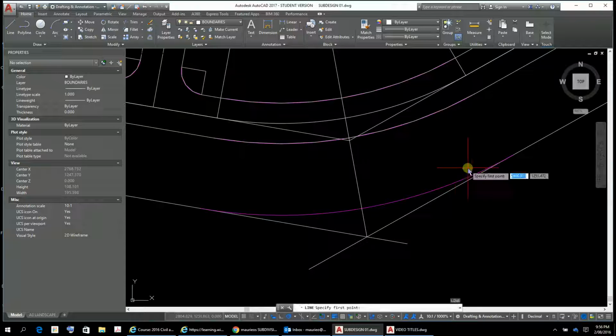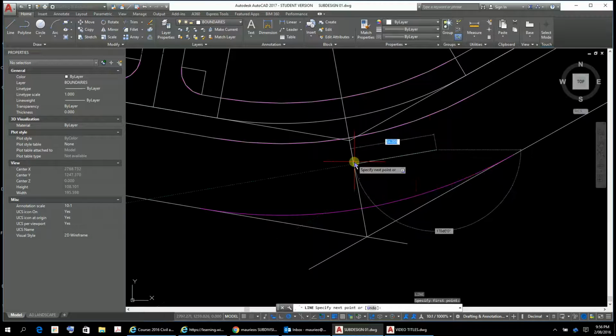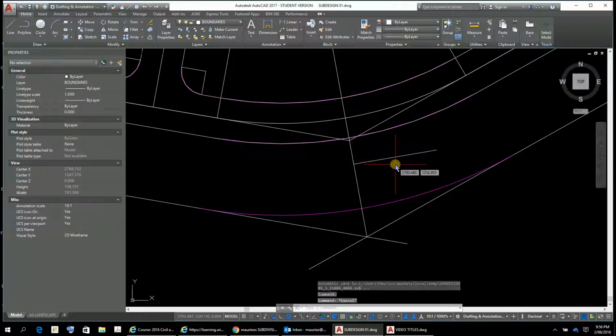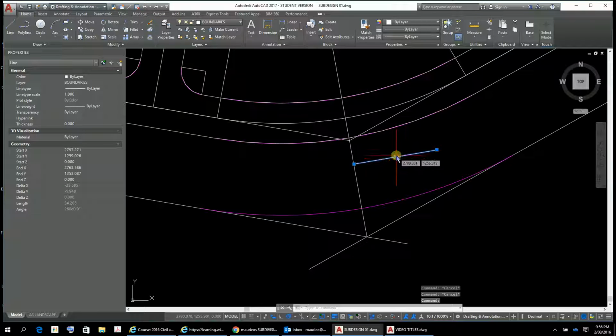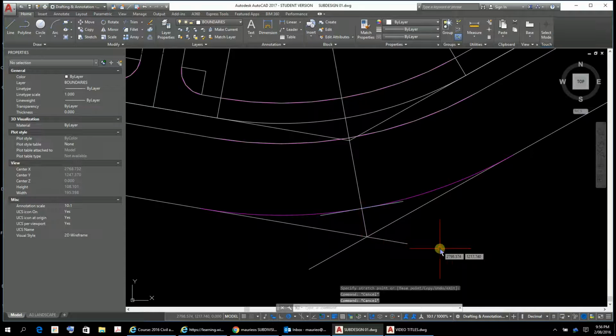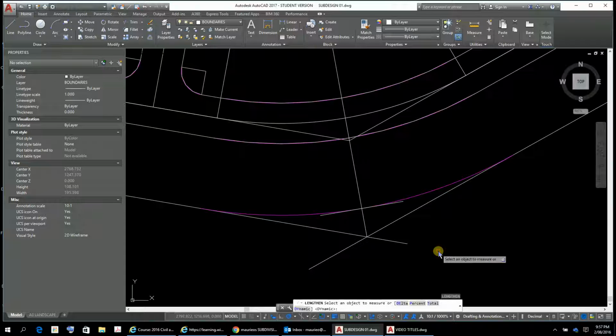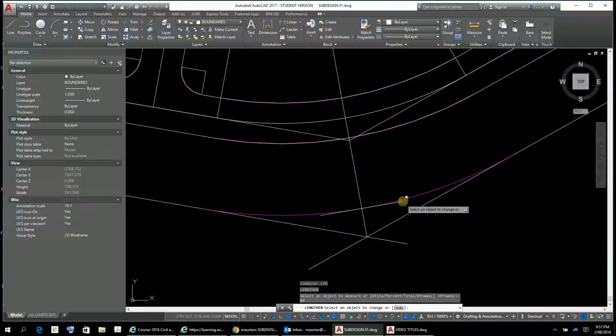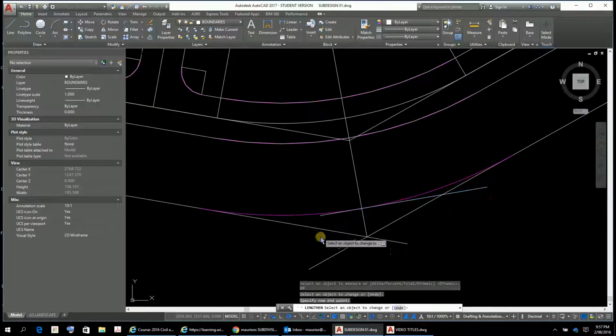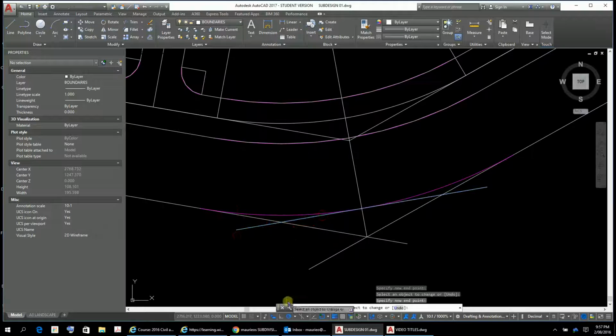Let's go alpha line, just in through to there into it. Is that it? There's my right angle. Yep. And I'm just going to grab this here, which will be in there like that. Pick that up there and move it so that it just clicks on there, the midpoint, and then I'm just going to do LEN for the lengthen and DY for the dynamic, and I'm just going to clip that through there like that, and clip that through there like that. So that will sort of give me the boundary of the back of my module there,